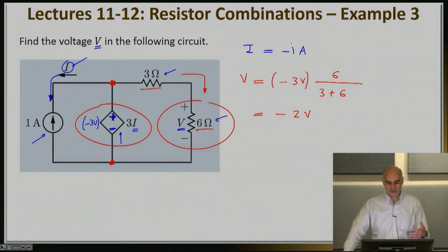There isn't. You have to go step by step. I just demonstrated here to essentially apply some type of voltage or current division to find the required voltage or current. So don't make the mistake of wasting time trying to think how you could get rid of that dependent voltage source by somehow combining it with the remaining resistances.